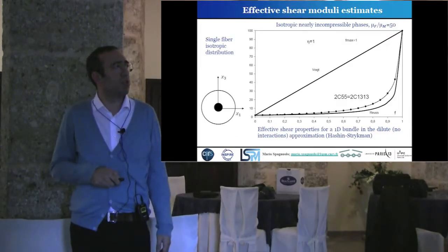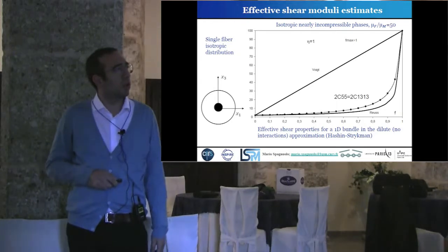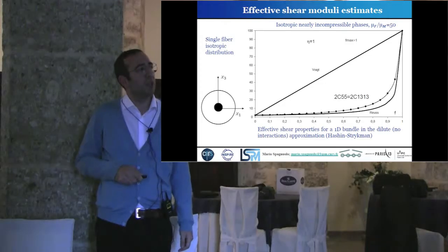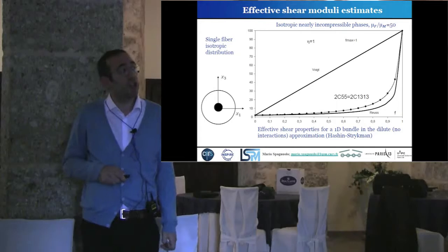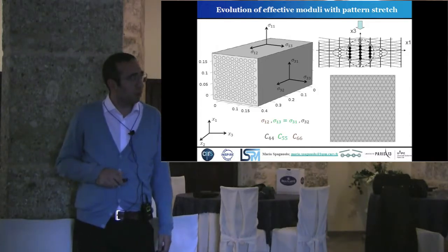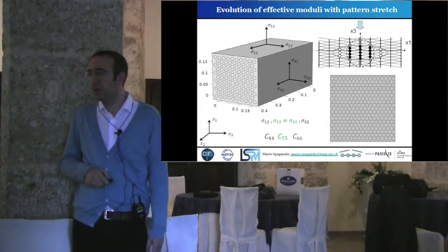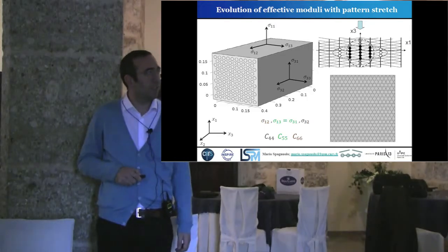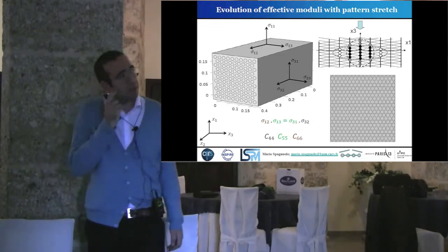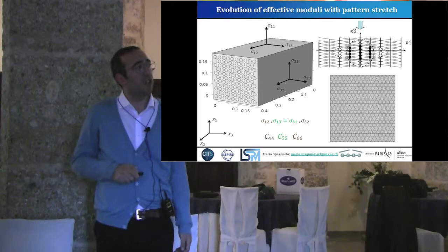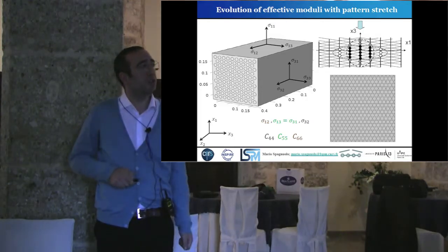I show you a calculus for the first one, for a single fiber in the matrix. So we have these different values of the elastic modulus, of the shear modulus of this composite material. And after I will consider the bundle. These are 2 different preparations for the numerical experiment. I should consider a 3D bundle, but it's analogous to this 2D problem if I want to know just the compression, so the Young modulus along these 2 directions, and the shear modulus if I shear in this direction or in this direction, which should be the same. So I will consider, for example, for the shear modulus only